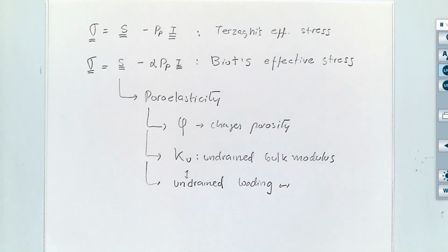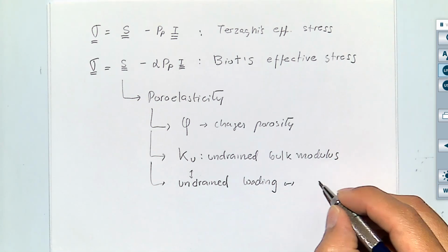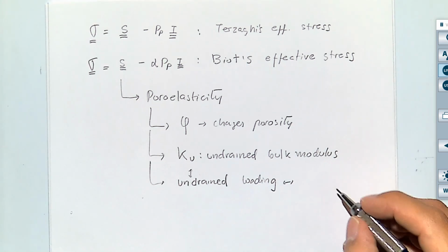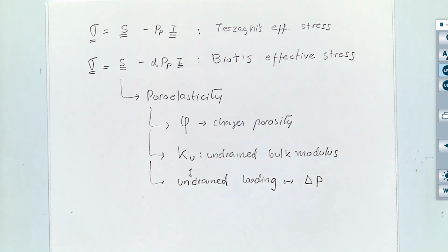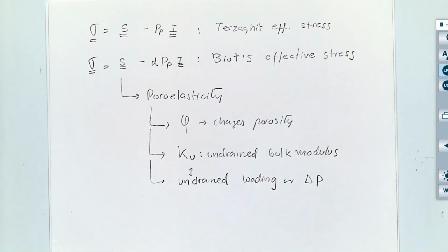What will happen to the pore pressure? It's going to increase, right? So with undrained loading, you're going to expect a change of pore pressure just due to the contraction of the rock. In order to predict that, also you need poroelasticity.